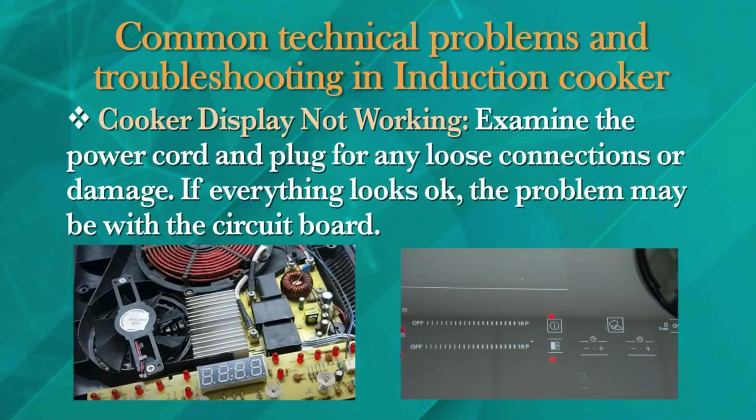Next is the cooker display not working. If the display of the cooker is not functioning, first confirm that the cooker is receiving power by checking the display for any signs of lighting up. Examine the power cord and plug for any loose connections or damage.